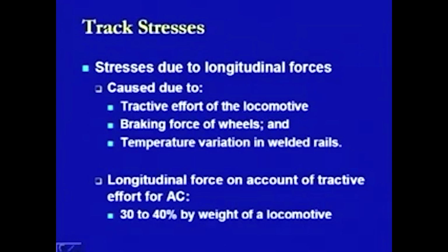These are the two things which can happen because of the temperature in any of the rail sections. If there is a certain movement, then it is a sort of creep condition, or if that movement is being resisted by the fastenings which are provided at the top of the sleeper, then that is going to create certain stresses. So, we have to look at the different types of stresses which are being caused because of the different factors in the longitudinal direction.